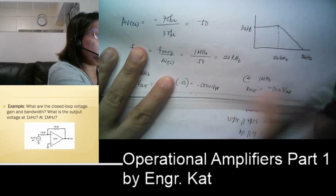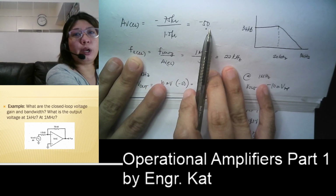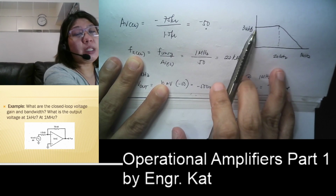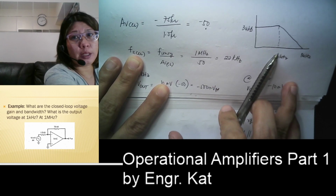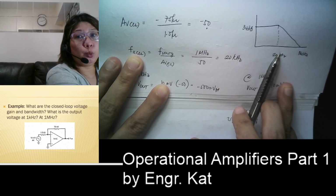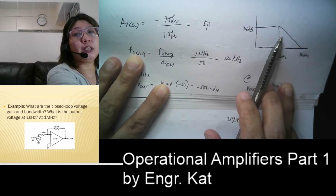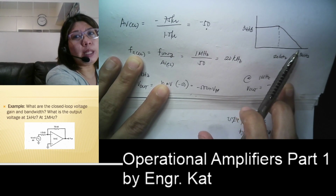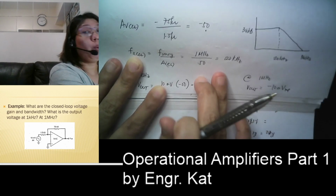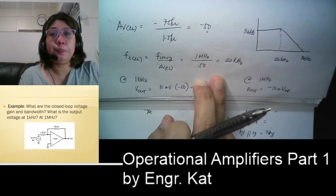So that means if we're going to get the value of negative 50 in terms of decibel, that will give us 34 dB. Okay, so from 0 up to 20 kilohertz, that is equivalent to 34 dB. So this is our F2. And from your F2, that will be your negative 3 dB point. So that will start decreasing at a value of 20 dB per decade until it reaches our 1 megahertz range. Okay, so that is what we mean by the bandwidth.